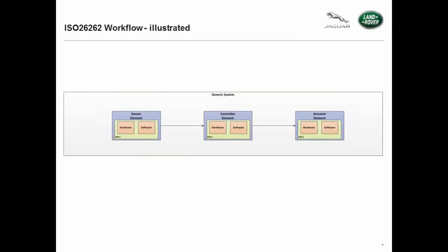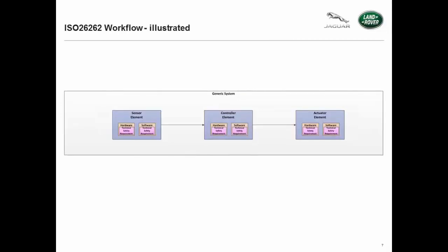Functional safety requirements, as indicated by the yellow box, are still describing logical level behavior to achieve safety. The technical safety requirements are then a little bit more detailed and describe more of a design solution. And these are then allocated to either hardware or software as appropriate, shown in those pink boxes.